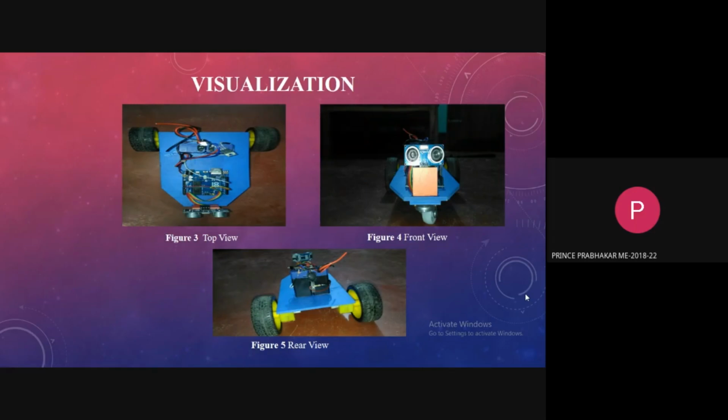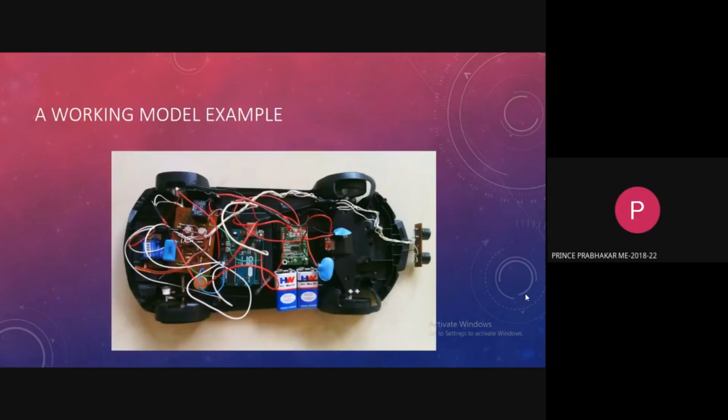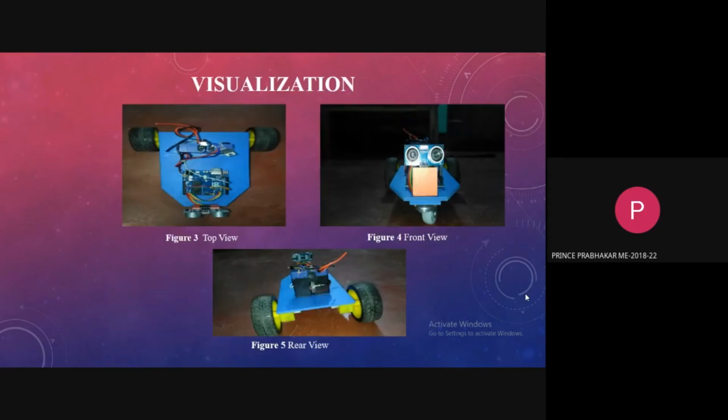The ultrasonic transmitter, which is placed in the front of the vehicle, continuously transmits the ultrasonic waves in a fixed range. The transmission transducer generates the ultrasonic waves from a 40 kHz square wave output generated by the Arduino, which is fed to the transducer after amplification. The ultrasonic receiver, which is placed parallel to the transmitter, receives the ultrasonic signals that are reflected from the obstacles. Then these reflected signals are fed to the Arduino. The Arduino calculates the distance to the object from the duration of time taken between the transmitted and received waves.